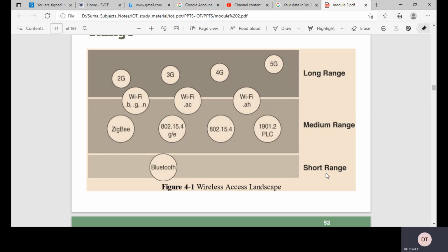power wide area technologies. These low power wide area technologies have the ability to communicate over a large area without consuming much power. These technologies are therefore ideal for battery powered IoT sensors. The other examples mentioned are found mainly in industrial networks: IEEE 802.3 over optical fiber and IEEE 1901 broadband power line communication are classified as long range but are not really considered as IoT access technologies.